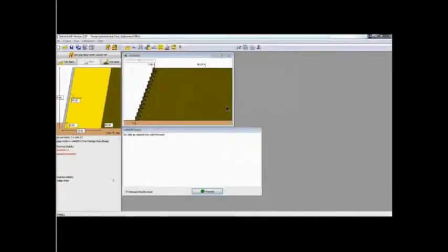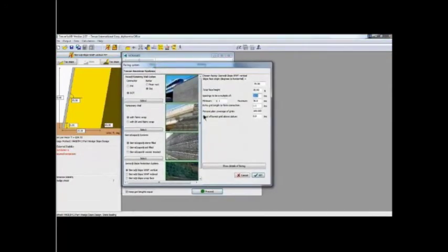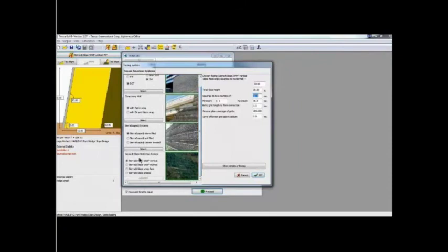The first step when designing a reinforced slope is to select which type of facing we're going to use for the slope. It's the same as the first step for a retaining wall. So we can click on either of these two facing system icons and bring up the facing systems window. Let's scroll down to the reinforced slope system, Sierra Slope, and we need to decide what facing angle our slope is going to be designed to.